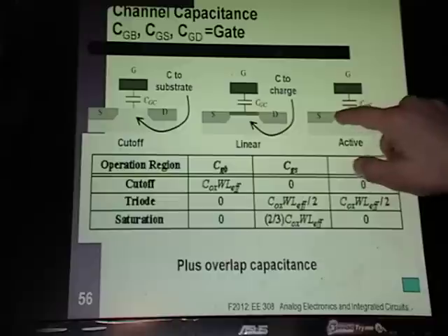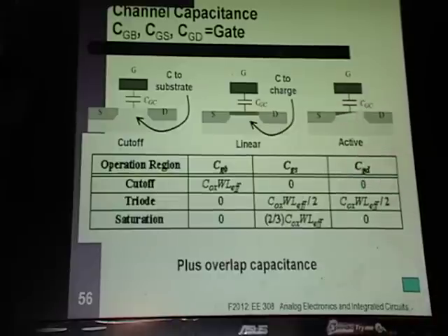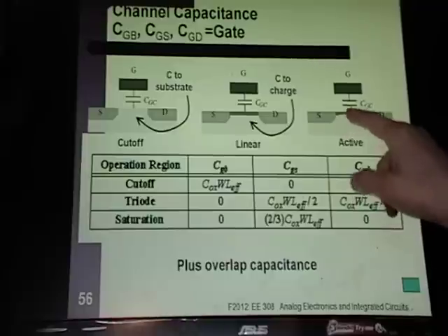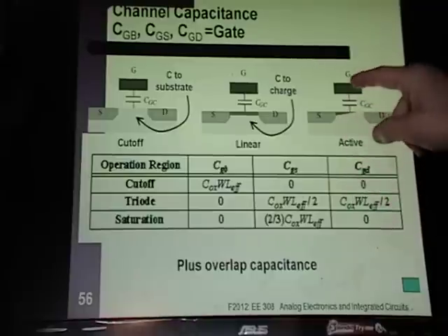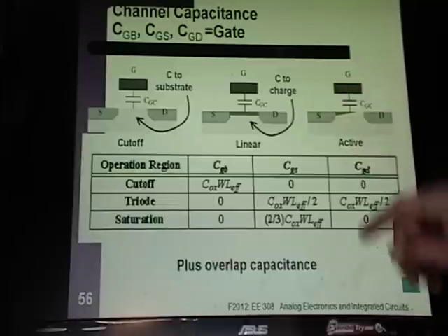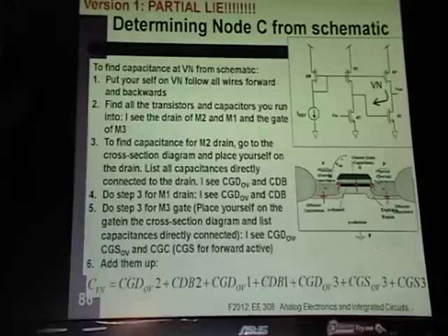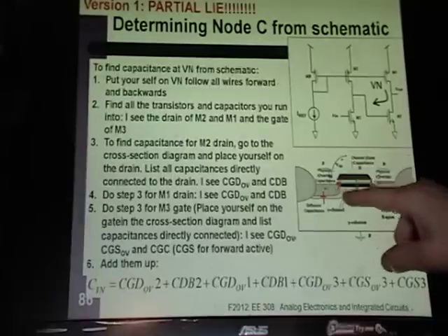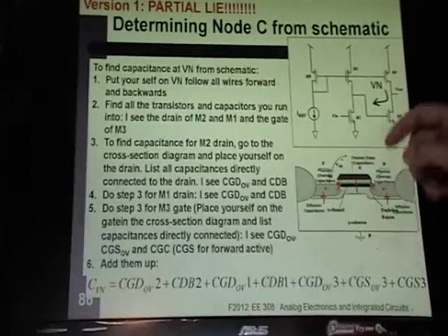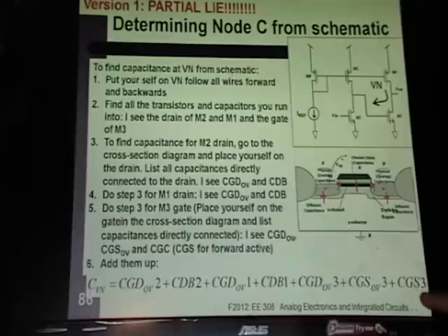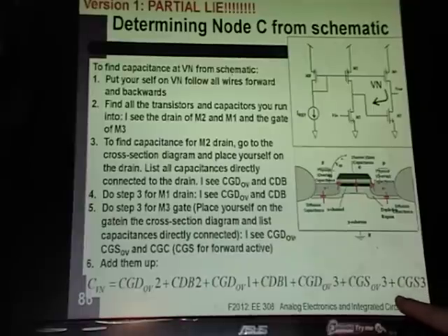Since they're kind of leaning up against the source, they just call this source capacitance. It's channel. It's electrons in the channel that the gate's coupling to, but in your textbooks you'll see it called the gate source capacitance. So I'm treating the overlap capacitance and the gate quote unquote source capacitance as different things. The gate source is the gate coupling to the electrons in the channel.